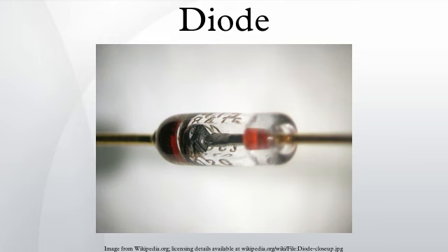Ionizing radiation detectors. In addition to light, mentioned above, semiconductor diodes are sensitive to more energetic radiation. In electronics, cosmic rays and other sources of ionizing radiation cause noise pulses and single and multiple bit errors. This effect is sometimes exploited by particle detectors to detect radiation. A single particle of radiation, with thousands or millions of electron volts of energy, generates many charge carrier pairs, as its energy is deposited in the semiconductor material.